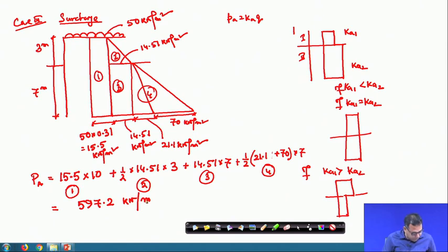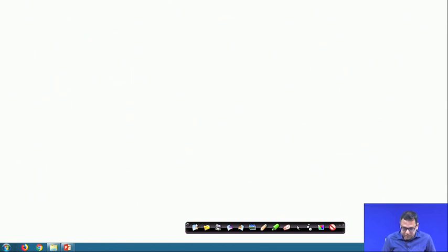Okay. So, next problem that I will consider, next example problem, where I am considering for the C phi soil. Till now I have solved one particular homogeneous layer with a phi soil. Now, I will consider a C phi soil, and we have to calculate what is the active earth pressure or PA. So, now all these things I have considered active. This is also the active case.